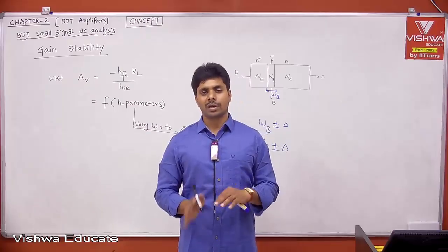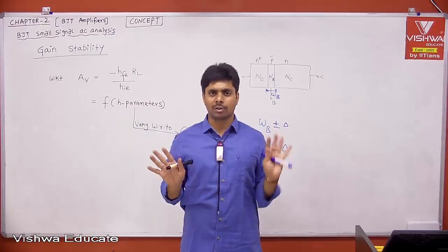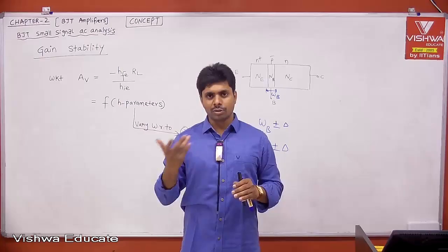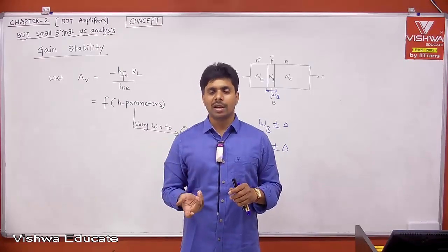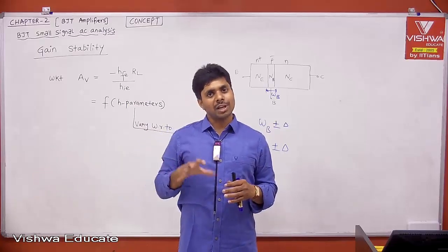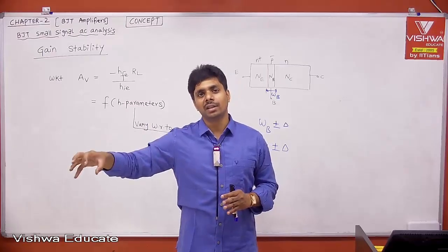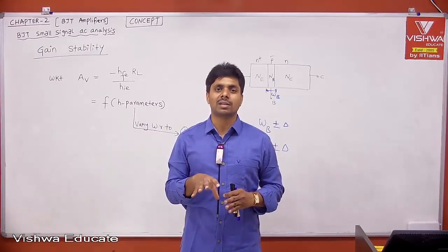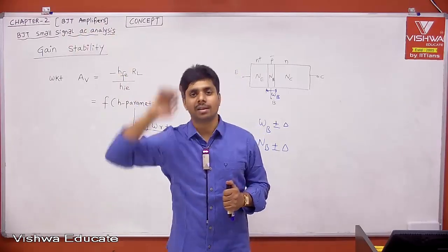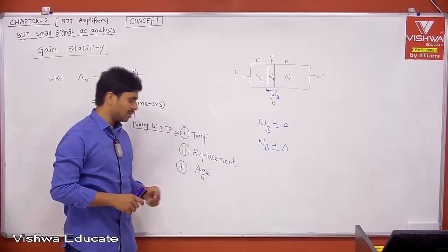Then you designed it today. We are getting some gain, some sound, some quality or some volume, whatever it may be. Now the same settings are given, but if you continue to play your audio amplifier, let us say after 3 years or after 4 years, whatever circuit you designed, whatever gain you got at time t equal to 0, the same gain or the same h parameters for the transistor will not be sustained. Therefore, we will not see the same h parameters after some time. Your h parameters change with respect to time. That is what is called age.